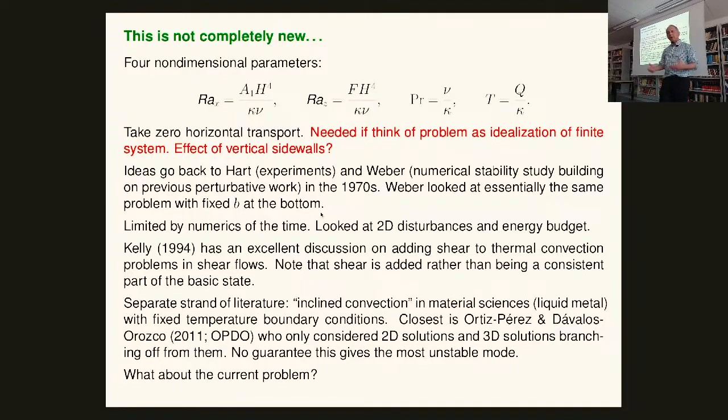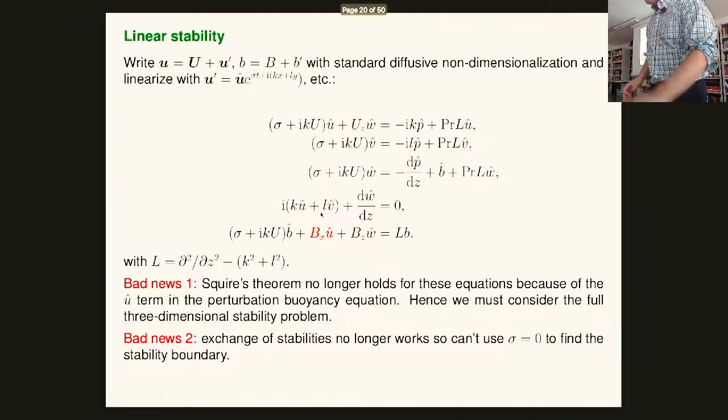All right, so what happens in our problem? Okay, so you got a great intern, and you give him the equations. So these are the equations we give him. These are our buoyancy equations, linearized about my basic state, capital U and capital B, which is here. And if you play games with Rayleigh-Bénard or with Orr-Sommerfeld, or Taylor-Goldstein, you will recognize these immediately because they look just like Taylor-Goldstein. Well, Taylor-Goldstein's inviscid, they look like viscous Taylor-Goldstein or Orr-Sommerfeld with stratification. I've got my three momentum equations, I've got my compressibility condition, I've got my buoyancy equation.